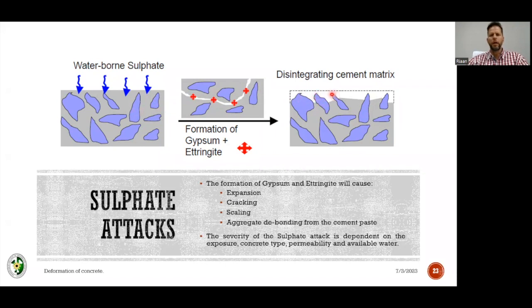An interesting thing is that for sulfate attack, generally dolomitic aggregate is preferred, because the dolomitic aggregate will not form these little islands or icebergs sticking out of the concrete. The dolomitic aggregate will also be worn away, sort of flush to the surface, and it actually prolongs the degradation of your concrete surface. Hence the fact dolomite aggregates are generally prescribed when you are looking at sewage lines or sulfate attack prone areas. If you lose this aggregate over here, immediately you have more surface area of paste available to react, and it can migrate quicker into your concrete.